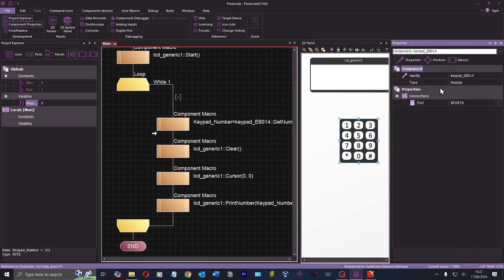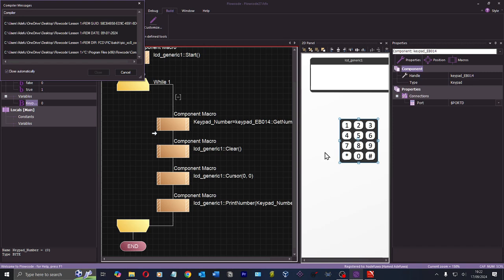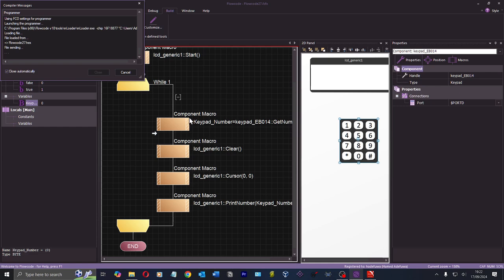Let's go to properties. Oh, port. Okay, set to port A. You set to port D. Try that again. In my mind, this 2D panel is for simulation, but it's not. It's for setting up Flowcode as well. So Flowcode relies on this 2D panel. Something I forget really.